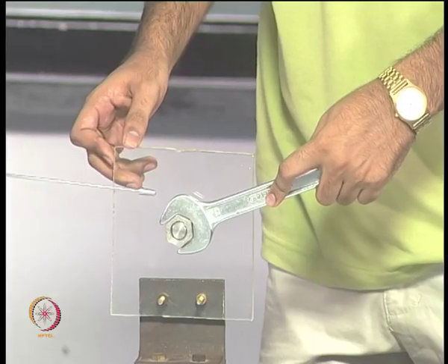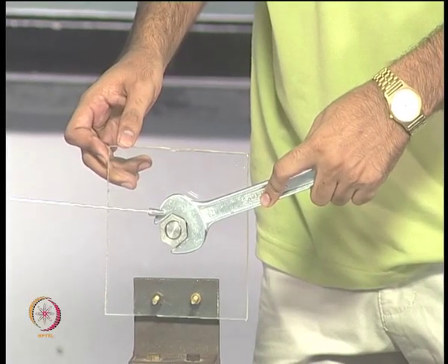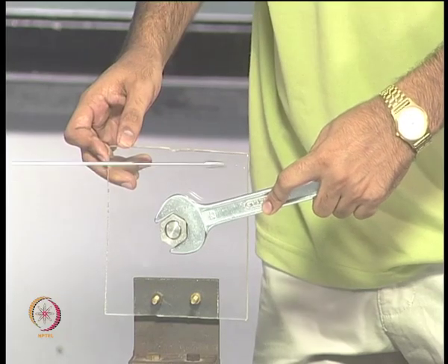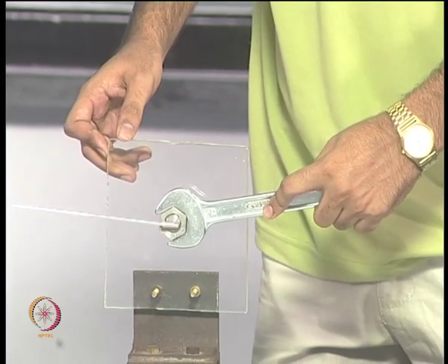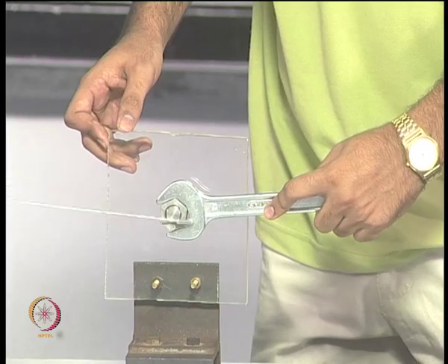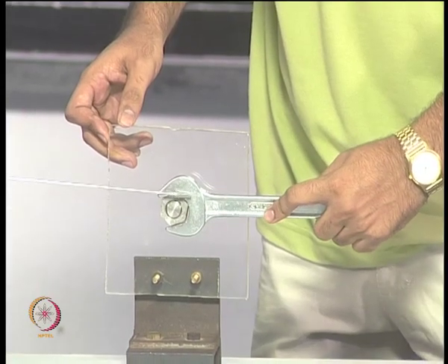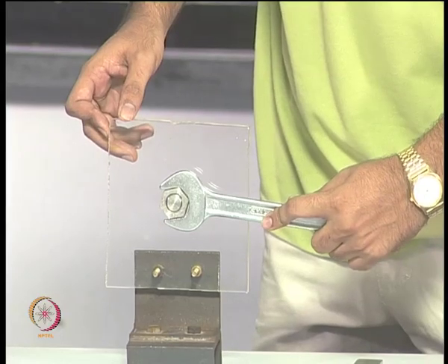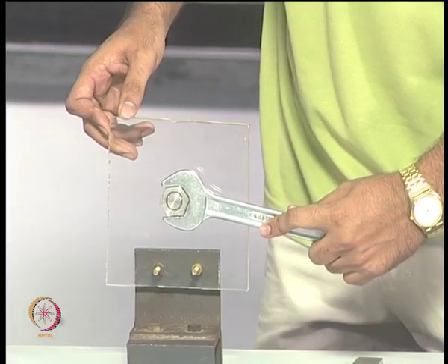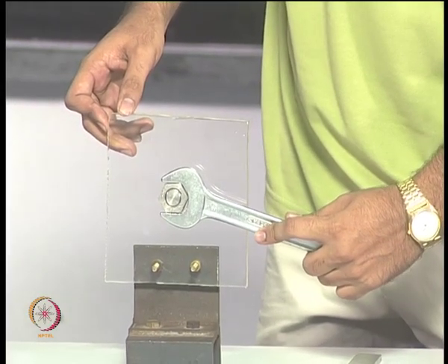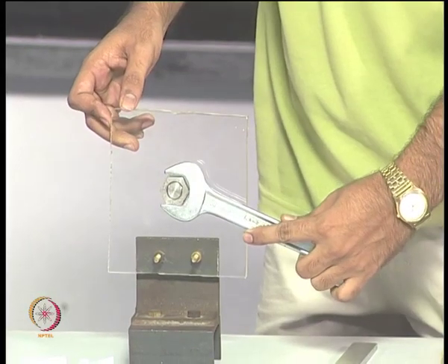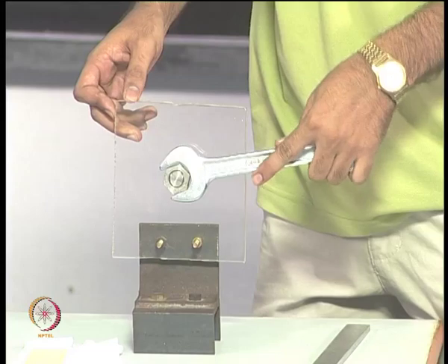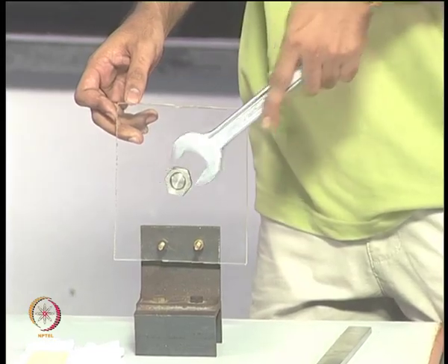And what you can say from strength of materials, because this is constrained here and you are applying a load here, some sort of a bending takes place in the member, and since you all know something about stress concentration, you could at best say there will be stress concentration in this zone and this is the load application point. So, certain general observations you could make from your knowledge of strength of materials. Because the geometry is complex, you cannot solve it by strength of materials, even theory of elasticity will not help.